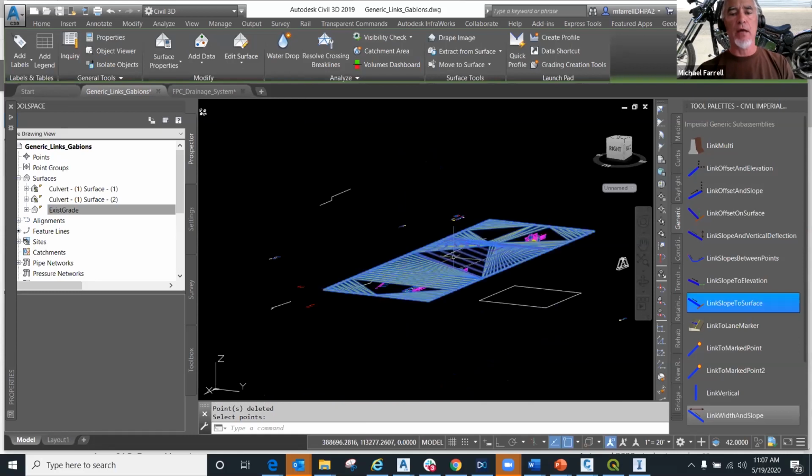So you can use the surface properties to set a known good elevation range to include or exclude data that shouldn't belong in your surface in the first place. Okay?